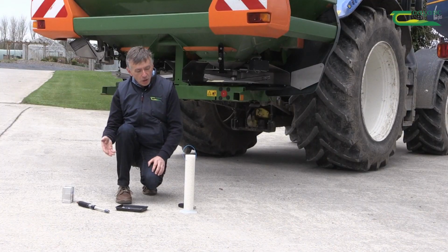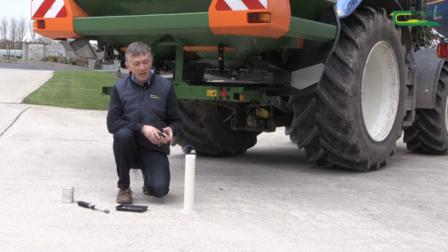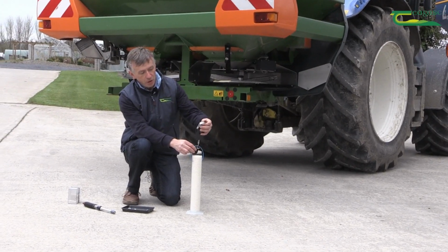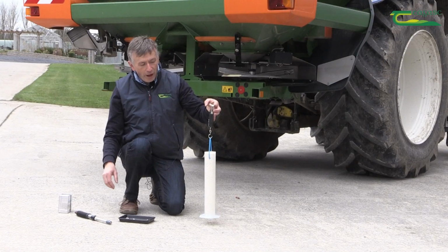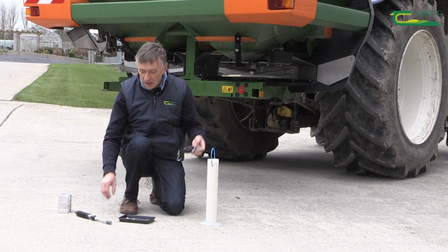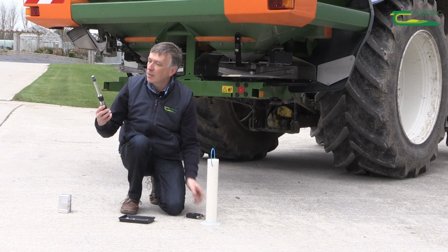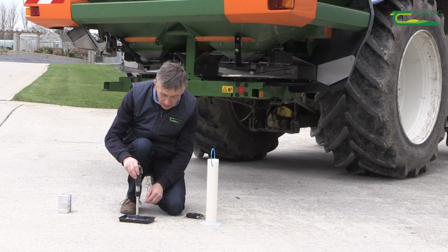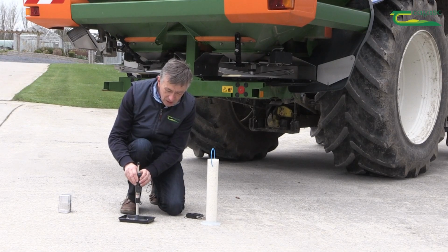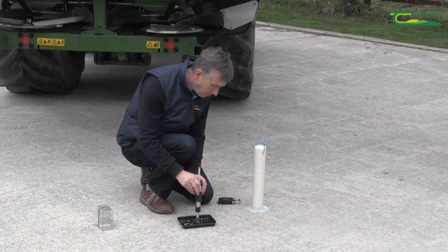Okay, the two other characteristics you need to know are to get the density of the fertilizer, which you can do by weighing an actual known volume, and the final point is to get an indication of the strength of the particles by using a simple strength tester like this here, where we measure the force required to break a particle of fertilizer.